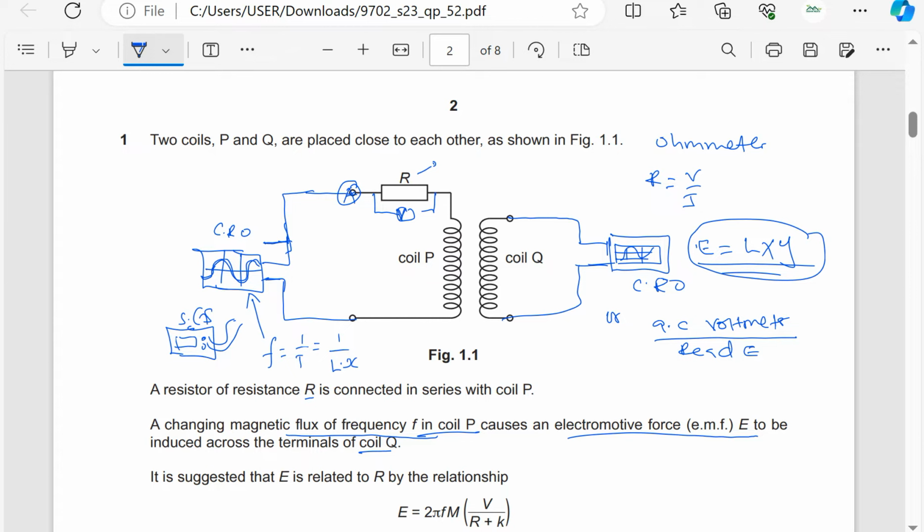Okay, then of course these coils, first of all, there should be a large number of turns to produce a large EMF, and the number of turns should be constant. Secondly, to produce a large induced EMF, you may need to put an iron core into this coil. So you may need to put an iron core to concentrate the magnetic flux.